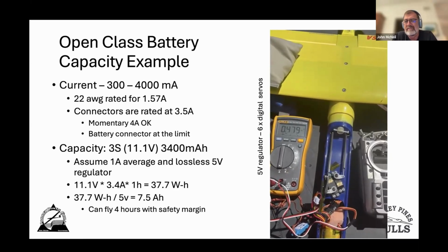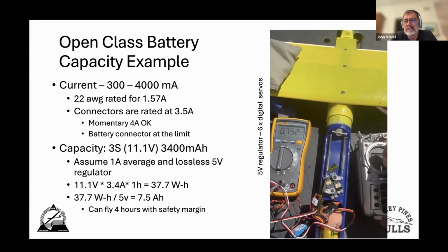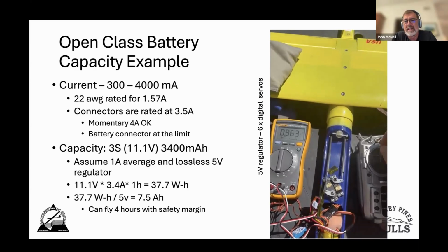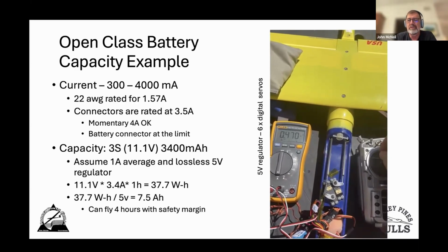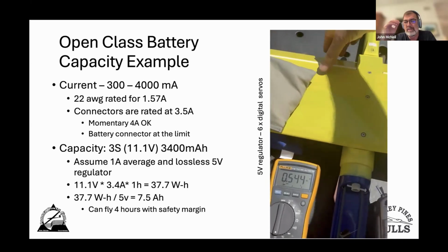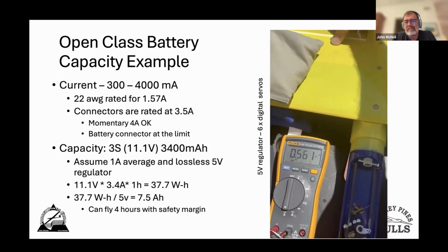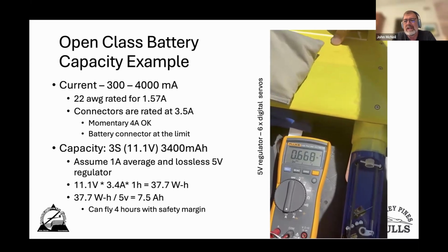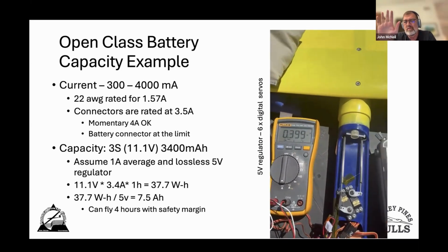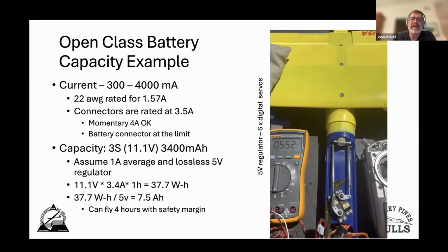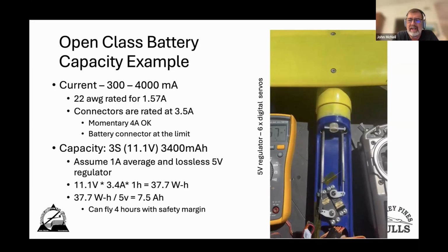I'm just kind of wiggling things around. You're looking at just over half an amp. And then if I move the flap servos and nothing else, you see we got to an amp, just moving them with no airflow, so unloaded. Now this is static load. I didn't have enough hands. I should have got someone else to hold the camera. I'm pretty sure that if I had held back while the flaps were lowering, I'd have gotten another amp out of that.